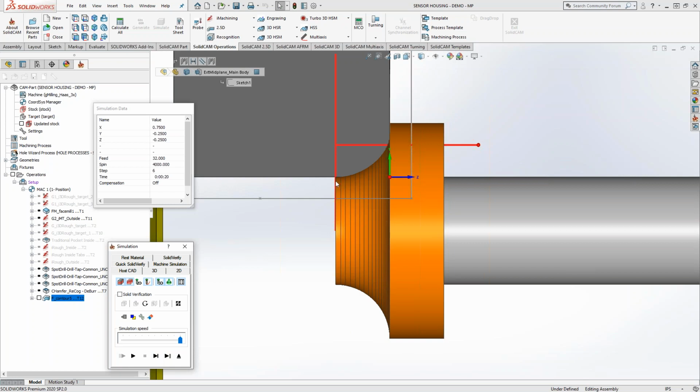So what Kevin has done is, if he says that this is actually the diameter to ride off of, then that is still the bottom corner of the tool. So this is one way to do this, but overall, for a shape tool, you're not always going to have a nice tip like that you can follow. You might have a unique shape, kind of like the railing example, because the shape of the tool is not always going to fit exactly the chain that you want to follow.